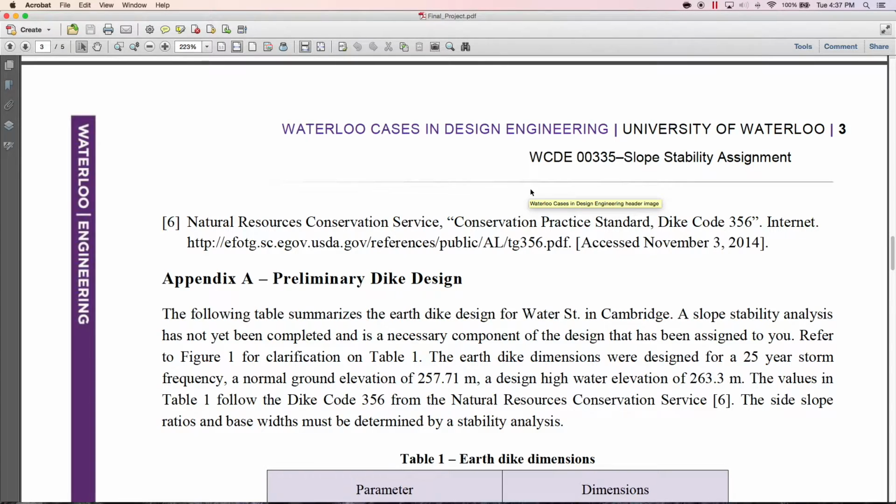Okay? And now, because we are going to perform flow analysis, we have to consider this boundary far away, but far away means far enough just to guarantee that these parts of the model are not affecting this part.